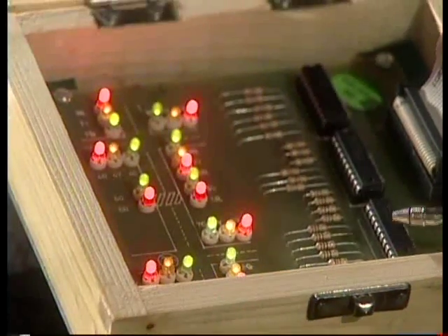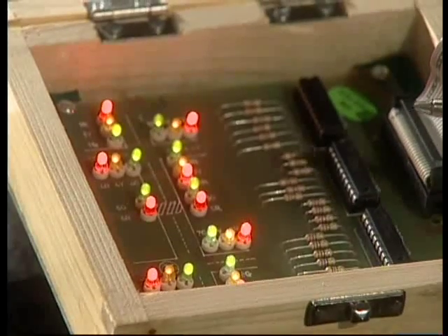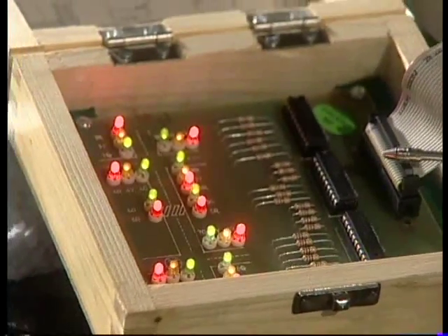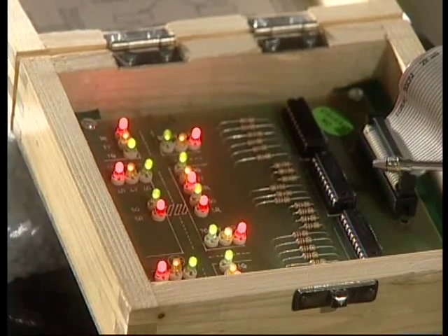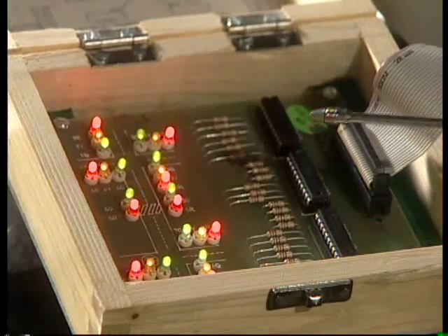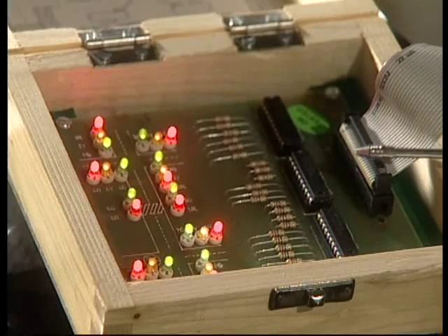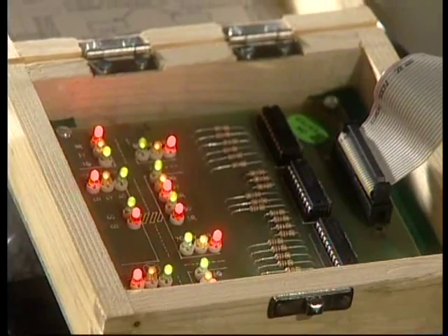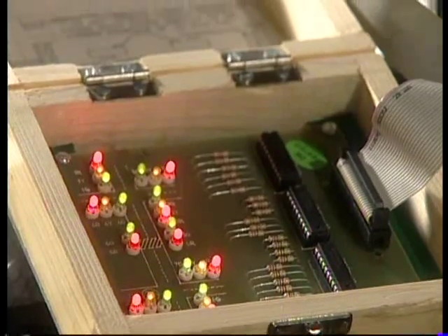It is because I am making use of 8255, and when 8255 is activated, it makes all its output pins high, hence all LEDs are glowing. You see, this is connected to the 8255 output through a flat ribbon cable. This is 8255. This is another type of microprocessor trainer, an 8085 microprocessor trainer only.